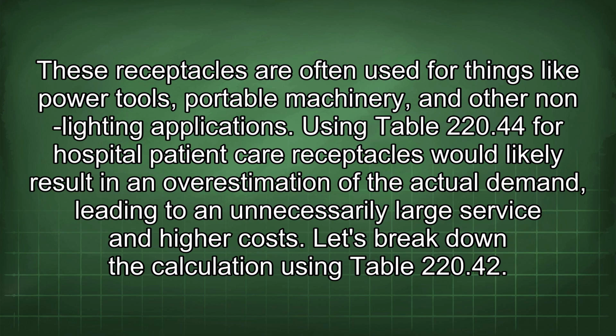These receptacles are often used for things like power tools, portable machinery, and other non-lighting applications. Using Table 220.44 for hospital patient care receptacles would likely result in an overestimation of the actual demand, leading to an unnecessarily large service and higher costs.